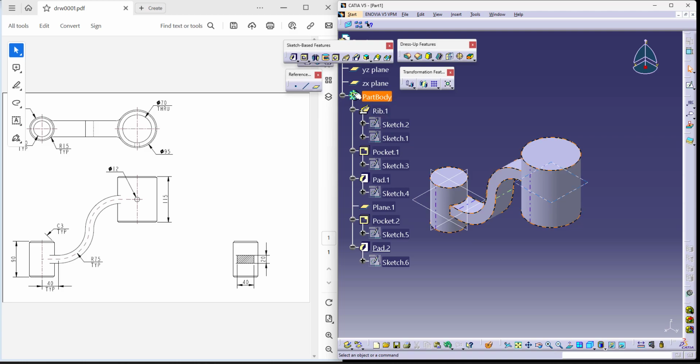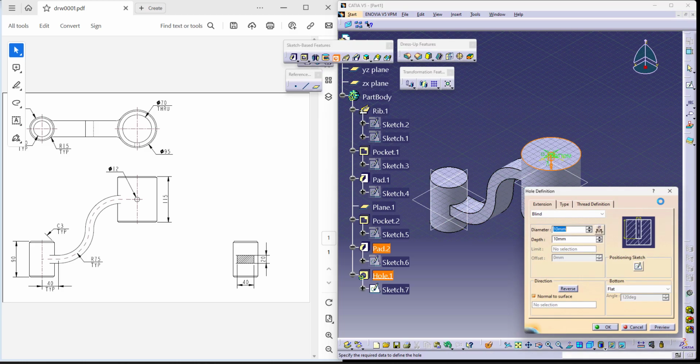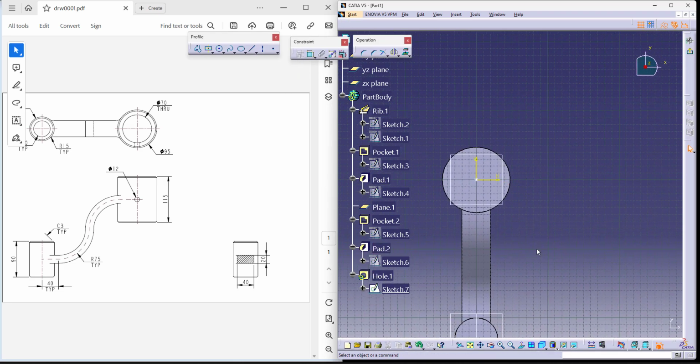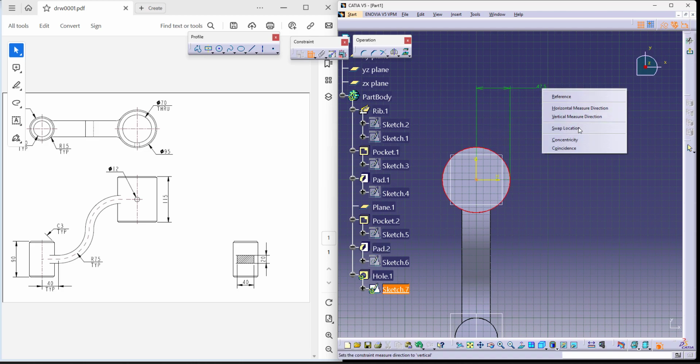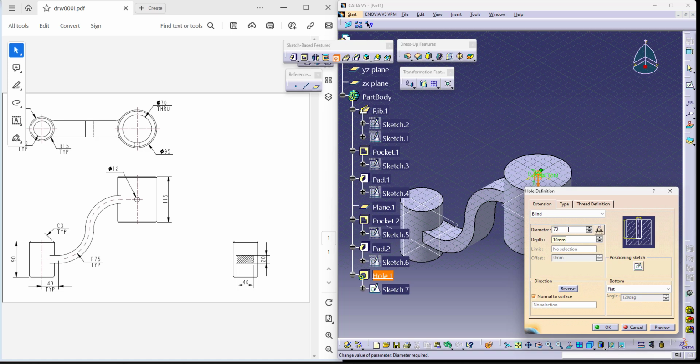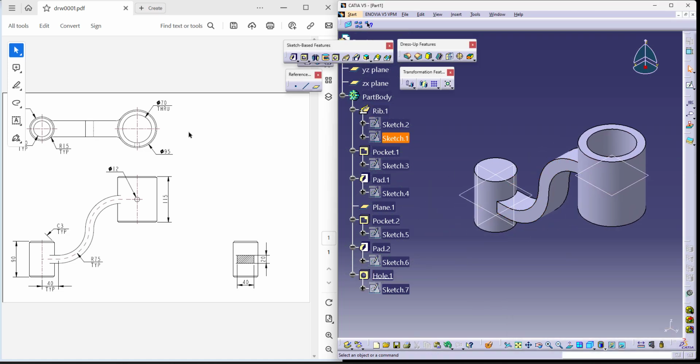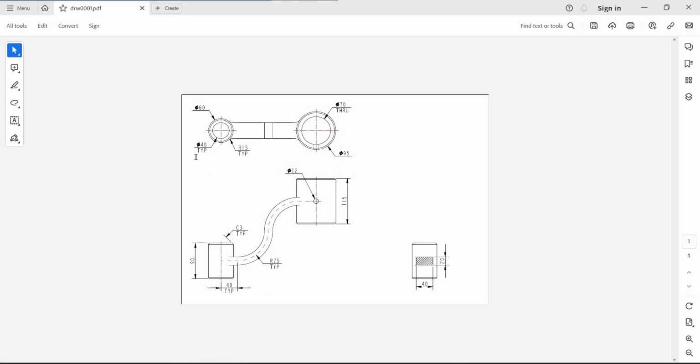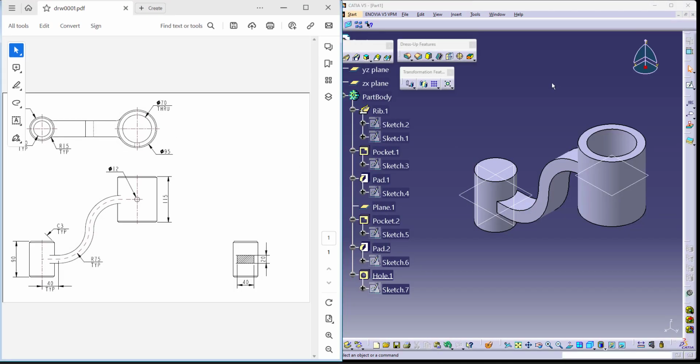You have 70 hole through, so let's try to give that. We need to give holes. In the end, we need to give your finishing operations, which are your chamfer and your rounds as per the feature based approach. 70 up to next. Similarly, there is a hole over here as well. Let's try to zoom in and see. 40. So I'm taking the hole over here.